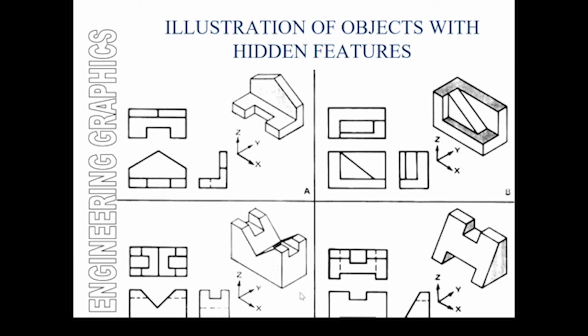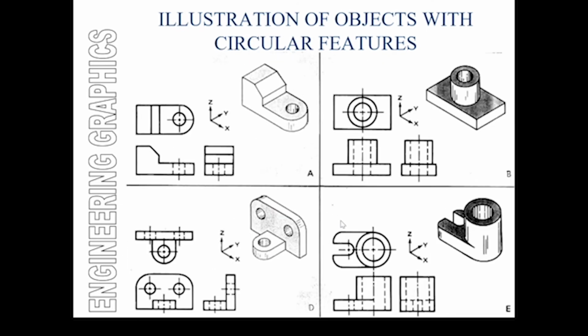And if you look at the same object on the right hand side, the notch here will leave a horizontal dashed line marking the depth of that cut. And if you look at it from the top, all the details are apparent and there are no hidden details. So they can actually be quite complicated at times to look at. However, as I said before, you acquire the skill by looking at these drawings over and over. Sometimes it's probably a good idea to just look at this, not worry about that, and sit down and try and draw that, freehand if you think.